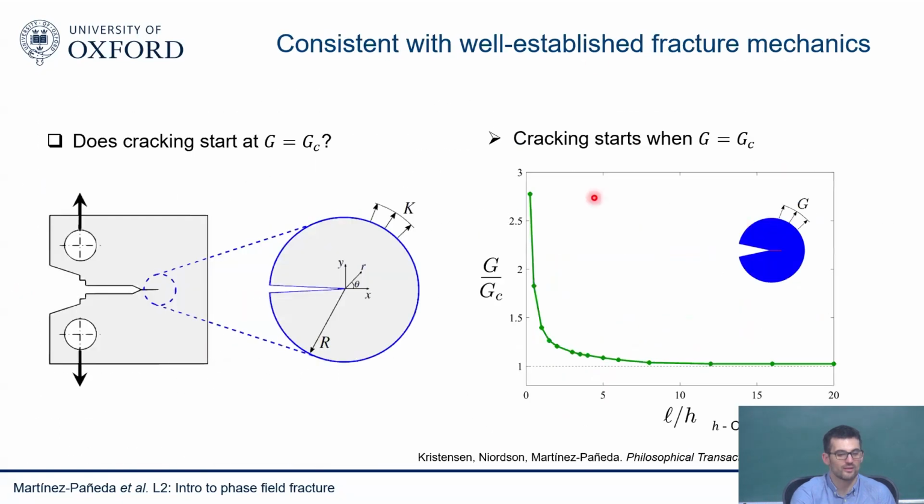And I said, what happens here is I do a simulation, I apply a load that I then convert into a K, and then eventually I see that when the crack initiates, my crack just grows because it's a linear elastic material, it's brittle, mode I, it's just going to grow all the way through.